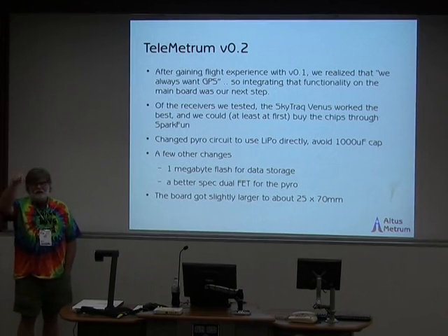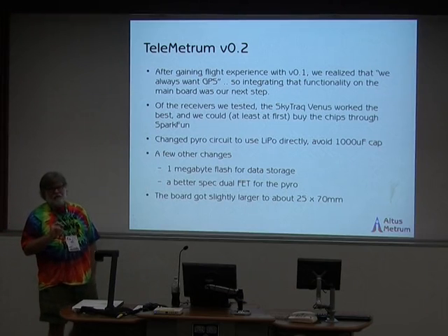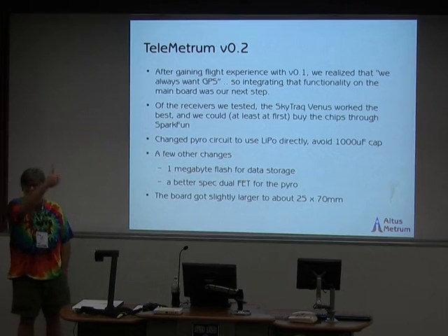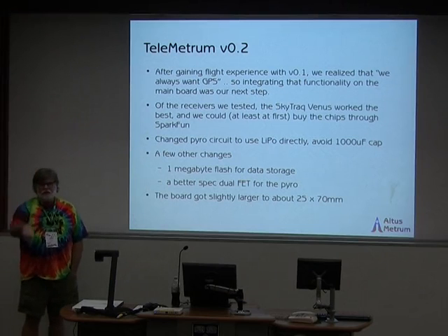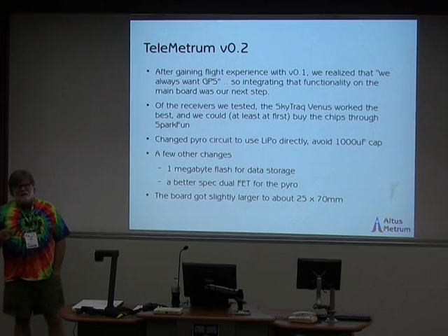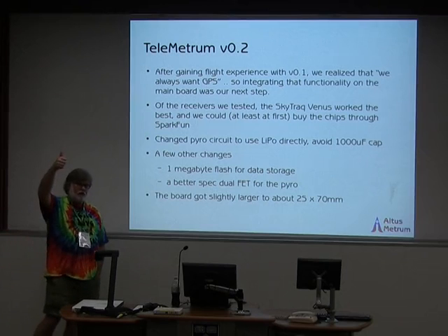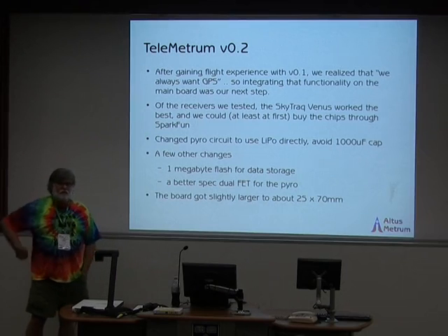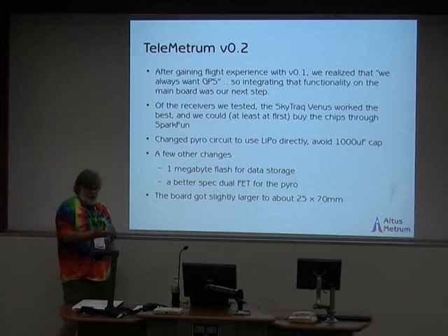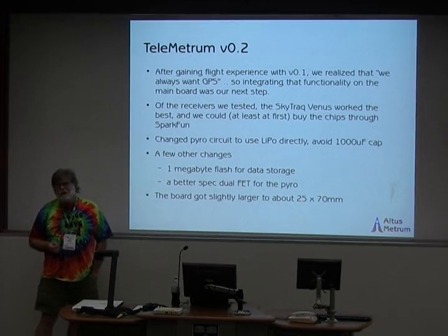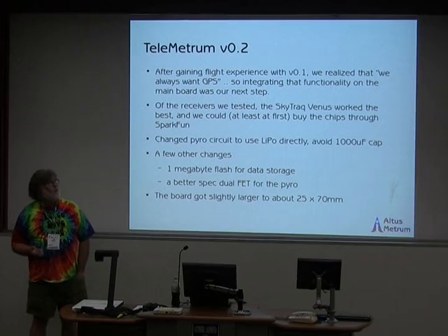It turns out that when it was coming back down, the GPS receiver hadn't actually figured out what that rapid change in Z was until the airframe was almost back to the ground. And it was really only the last data point or two that we received over the radio link that were anywhere near where the airframe actually was. If I remember correctly, the GPS chip's way of trying to figure out what was happening when it was being kicked in the ass hard vertically was to assume that it was being shoved due west. We could talk forever about GPS receivers, but the behavior of the firmware on the SiRF 3 parts was not appropriate for use in rockets.